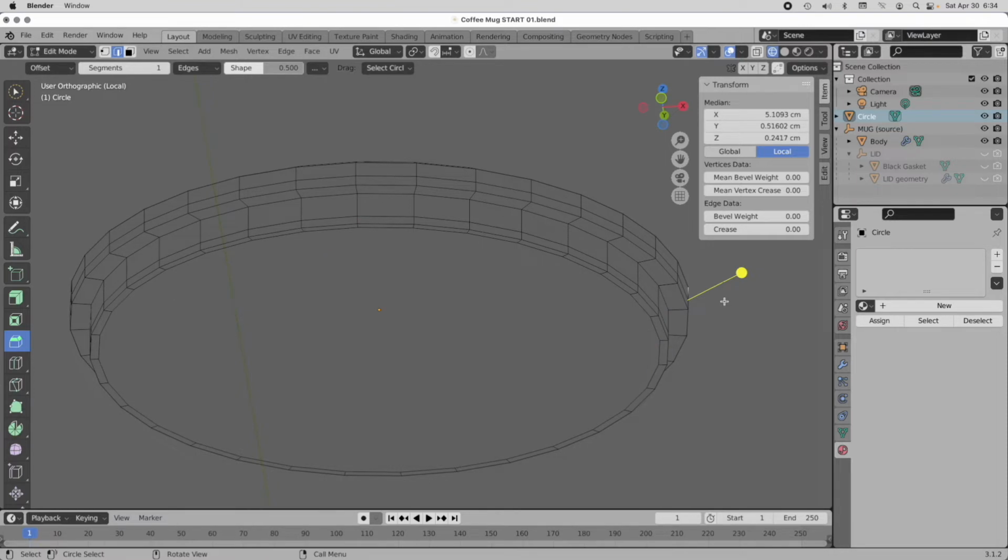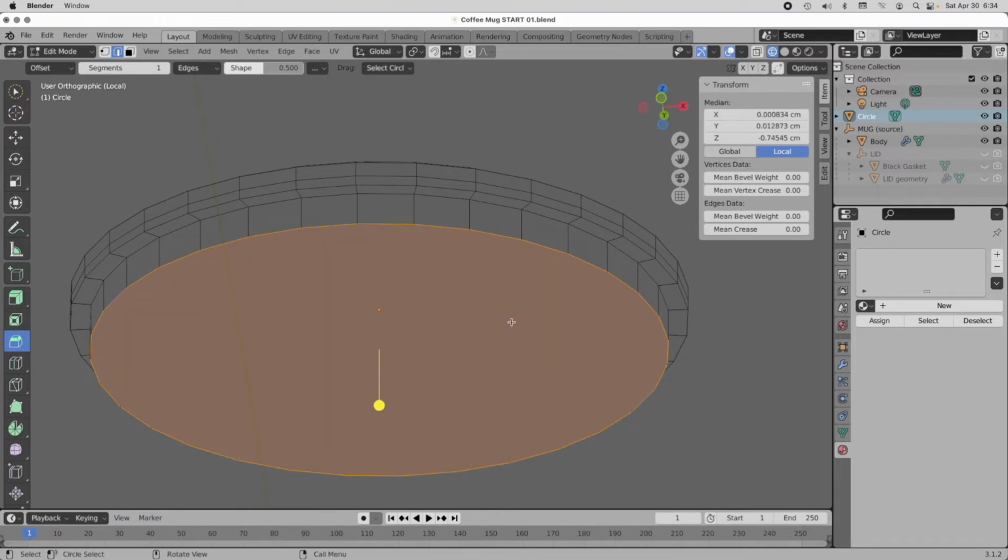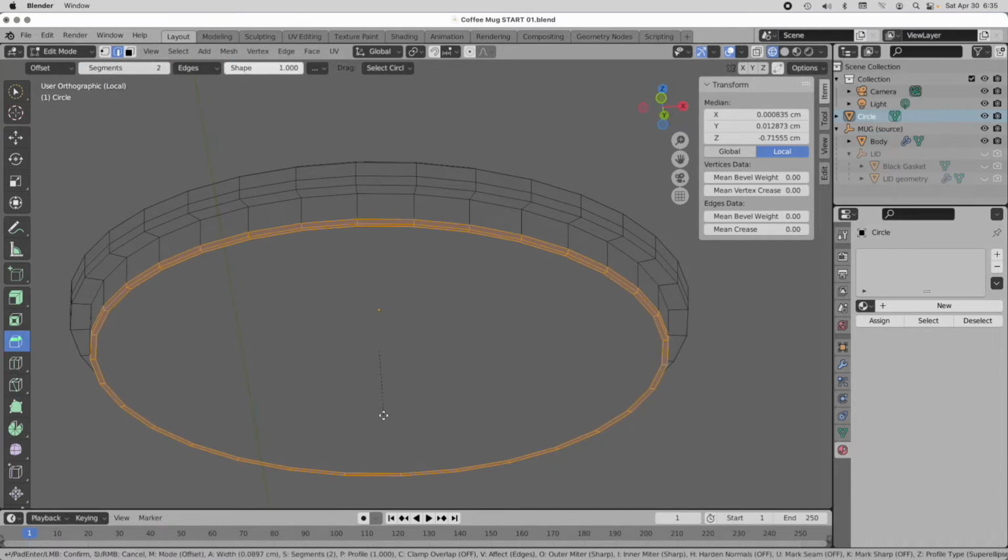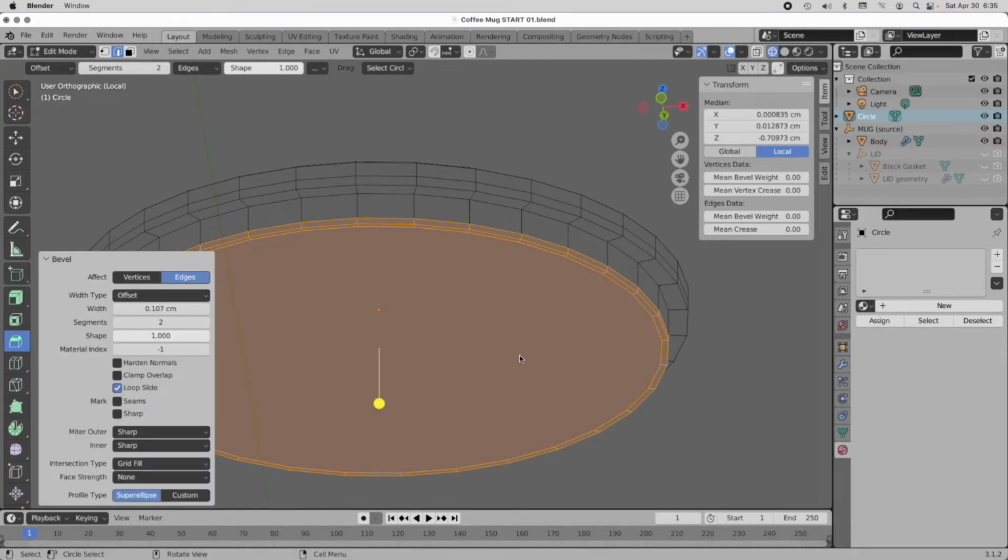Okay, so let me just show you this. I'm going to undo. If you want to create that shape from the very beginning, you can simply come up here and change this to 2 segments, tab, and 1, and then from the get-go it will produce that shape for you. I want a little bit of a rounding there, and this is where Subdivision Surfaces is great. It'll produce a little bit of rounding here with this very simple set of geometries.